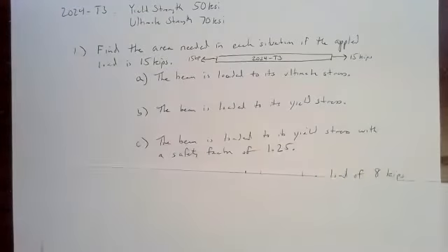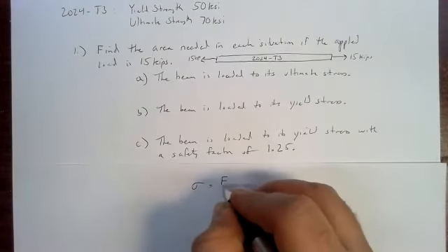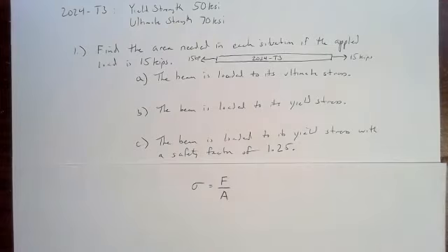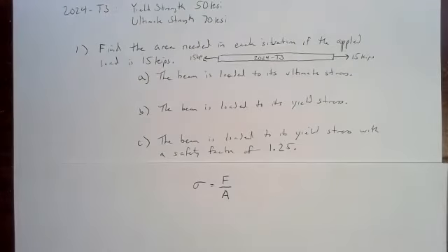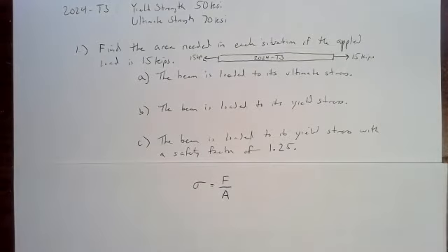So the fundamental equation is our definition of normal stress. More often than not, when working with strength of materials problems, if you don't know where to go, start with your normal stress equation. If it's a shear stress problem, start with the shear stress equation. But it's always going to involve stress, force, and area. You just have to figure out what you've got and what you need to solve for.